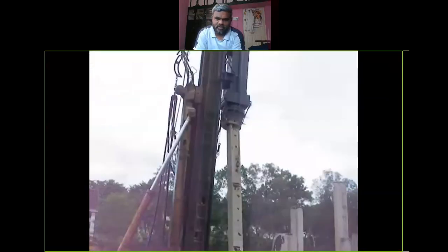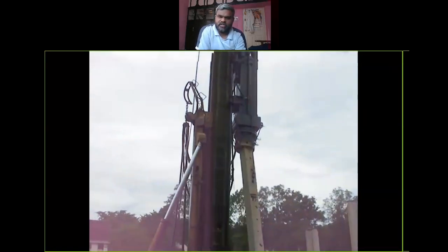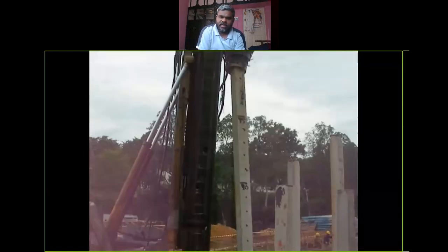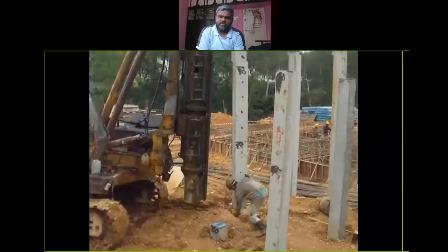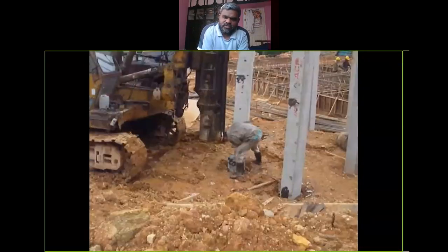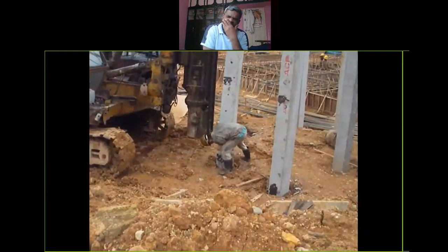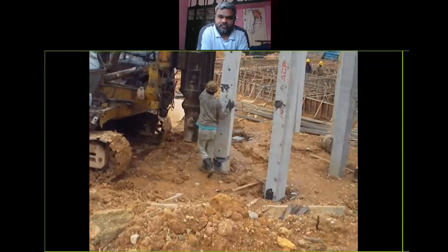This piling for a foundation is teamwork: all piles are joined together with a pile cap, and then the foundation of the building can be constructed. So the loads are distributed by all piles to the soil.